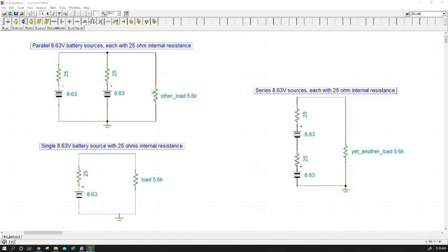And in that sense, for that situation where we had a low resistance in our load circuit, we were actually being limited by this internal resistance in series with each battery and got a benefit from putting two sources in parallel. So we're going to continue to explore this with a simulator where we don't have to worry about overheating a resistor, and we can really get a good idea of how much current will flow.